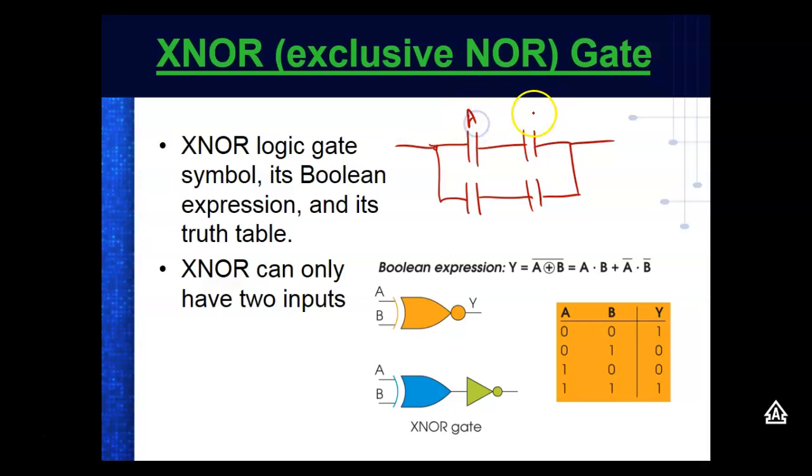I'm going to call this A, B. So let's make these two like that. So right off the bat, I don't press either button. So A and B are both false, so I will pass to the bottom one, right? So a 0, 0 would give me a 1.